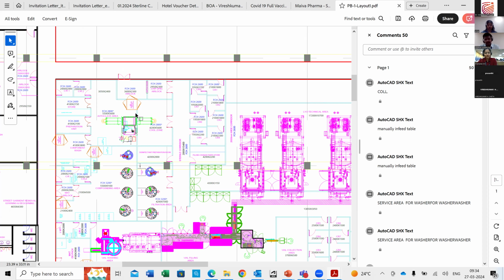So you will see a double door autoclave. Always remember, loading can be done at a slightly lower grade, and the unloading has to be always at a higher grade or the grade equivalent to your process areas. So if this was C, this has to be C. If this was B, this has to be B. If this was A, then you have to create an A area here, and that is important. The loading has to be one grade lower than the unloading side so that you can maintain the pressure cascades and the cleanliness of the clean rooms.